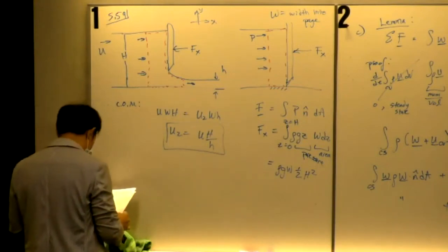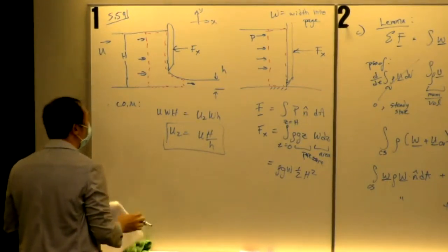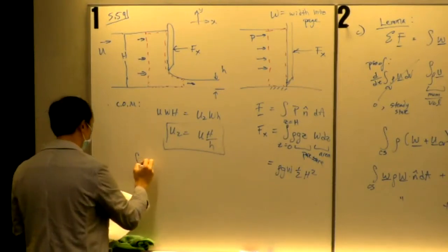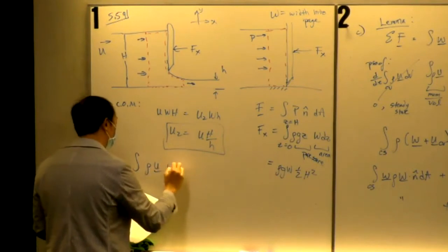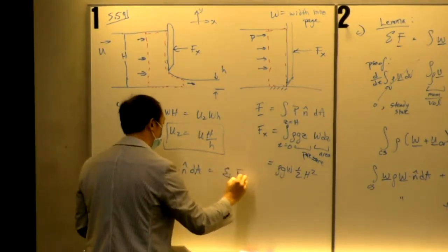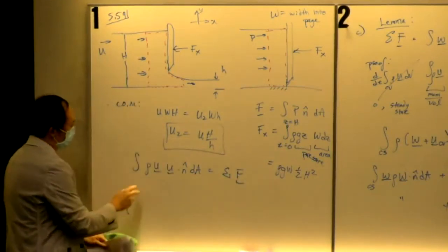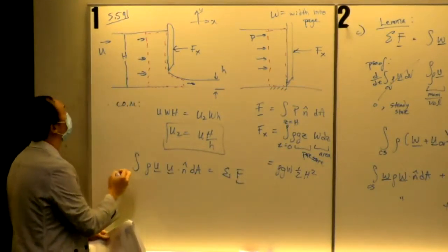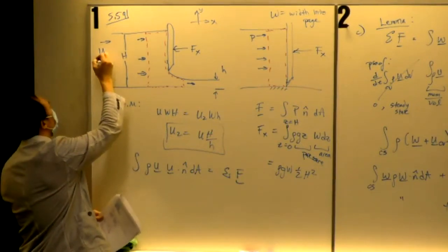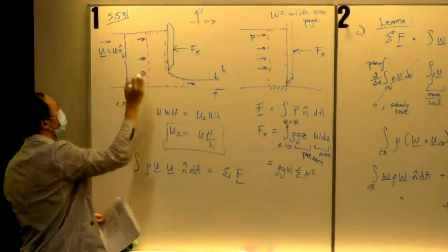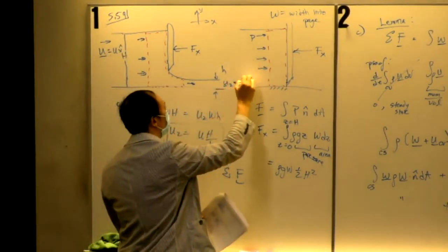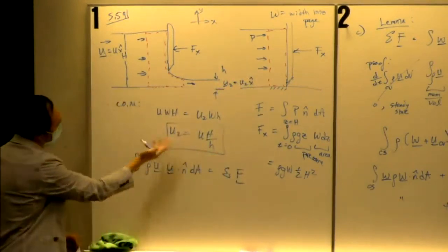All right. Now we got the magnitude U2. Now we got to use conservation of momentum. So we got rho U hat dot n hat dA is equal to the sum of the anchoring forces. The left-hand side: U is equal to U x hat, U2 is equal to U2 x hat. We can use those magnitudes later.